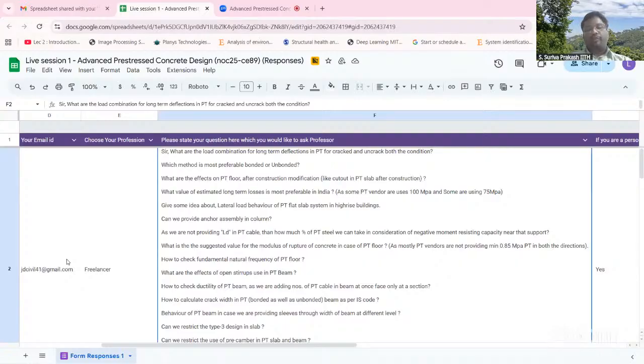For long term, obviously you have to include the effect of shrinkage-induced deformations plus the creep-induced deformation. Creep effects are considered by a reduction in your elastic modulus. And shrinkage also induces some additional curvature. We have talked about how, once you know the shrinkage curvature distribution, double integration of the curvature will give you the deflection. That way we account for the long-term effects.